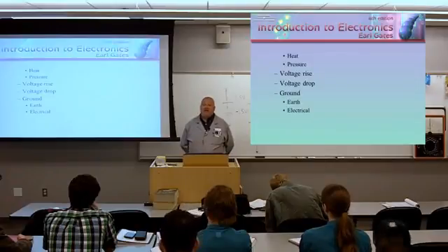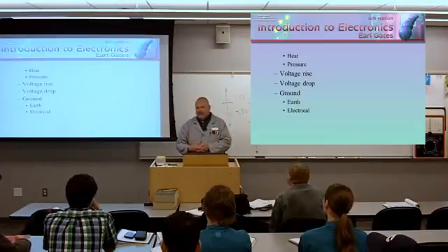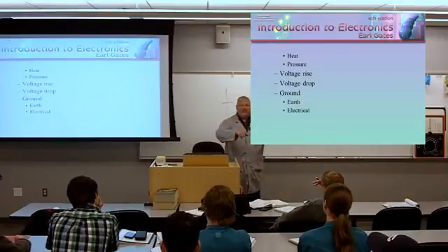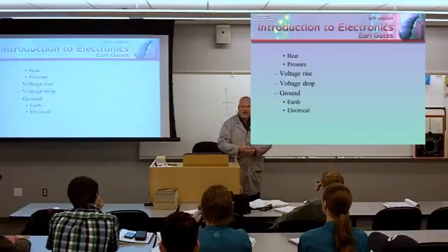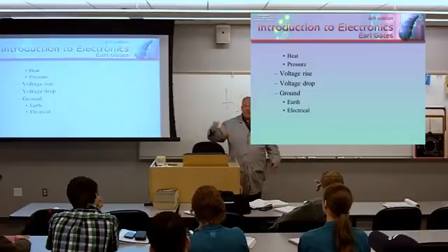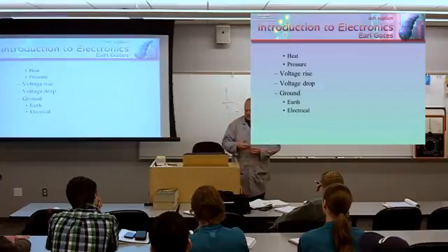Am I being silly? Am I keeping it basic? Yeah. But you know what? I have fixed in my career dozens of problems where the symptom was that the equipment doesn't work right. What's the first thing that I do? Check the voltage coming in. If the voltage coming in isn't good, it's not going to work right. Then you got to find out where the missing voltage is. Maybe it's a brownout. Maybe the power company is having a problem with generating power and giving you the feed. But those two always need to equal each other.